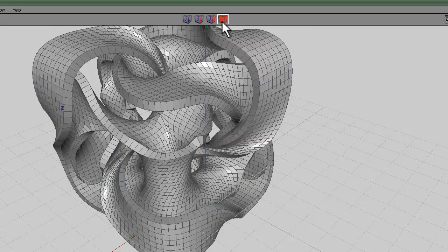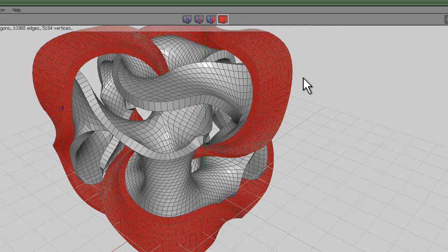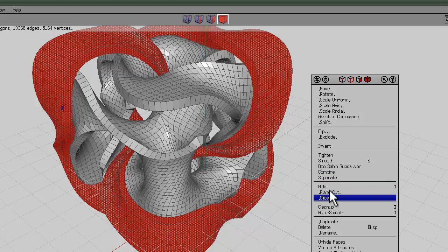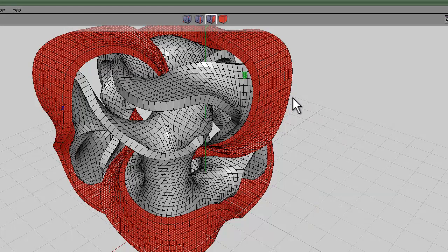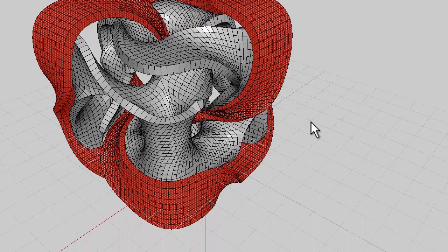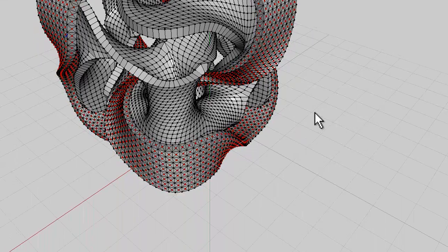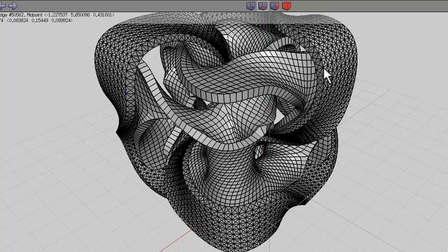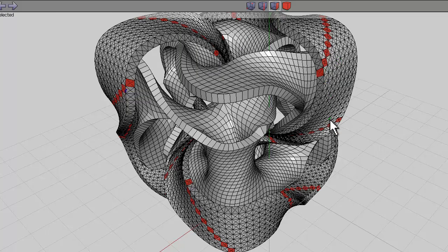Or likewise, you could select the entire object, and if you use face selection here, inset, and then just inset it a little bit, it doesn't matter, then collapse that with this outer one. Because of the way it runs, you can then use these lines that are created by the cross sections to create loops. You can see that it comes out with teeth on it if you do it this way.